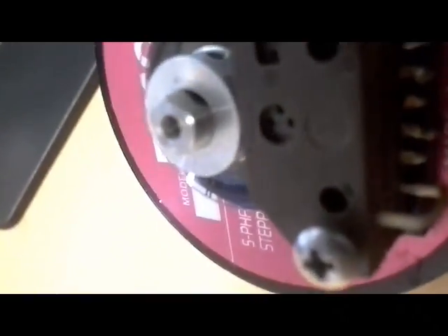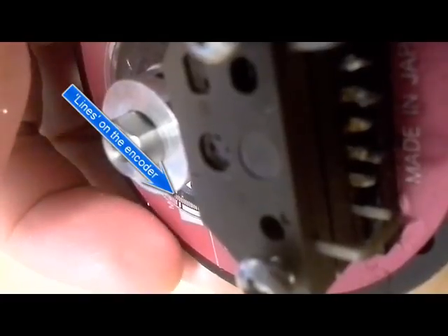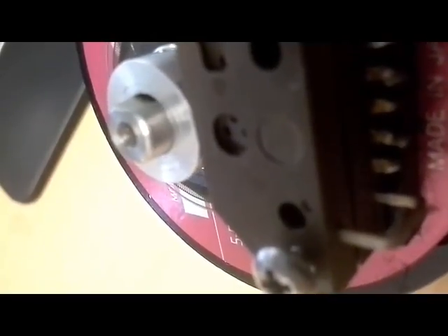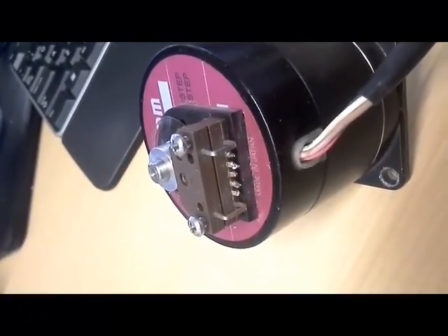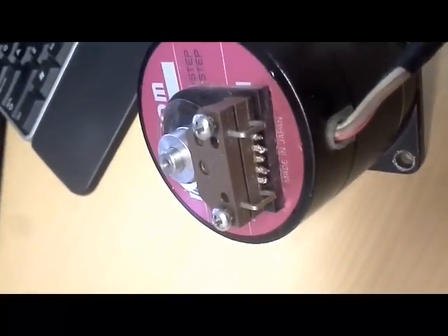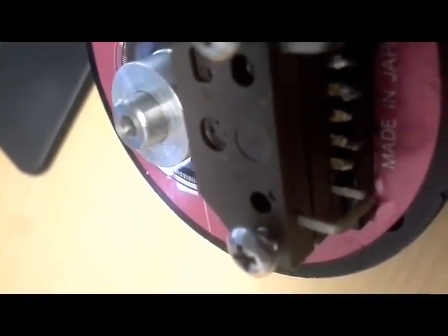Now, if I turn the camera at just the right angle, you can kind of see, there we go, right here, that these marks on the disc alternate dark black lines and clear lines. As the shaft rotates, the light shines through the clear lines and the light does not shine through the black opaque lines. Now, in the top of this brown plastic piece up here, there is a light sensor like a photocell that is detecting the pattern of bright and dark pulses that it gets as this disc rotates and alternates its clear and opaque lines.